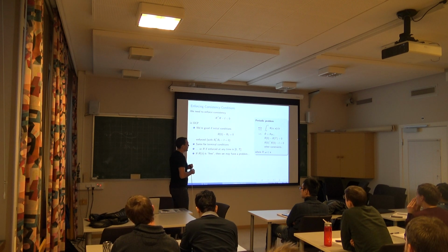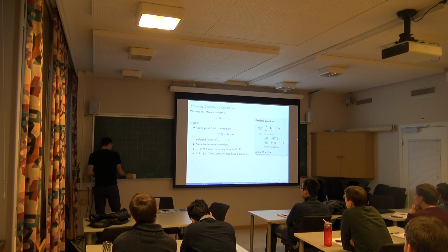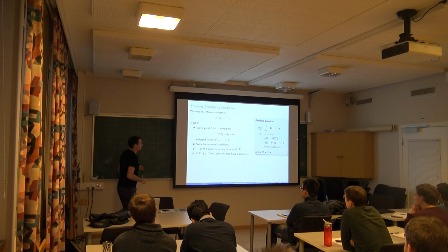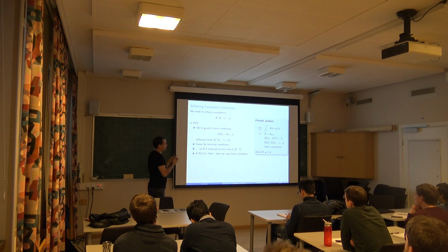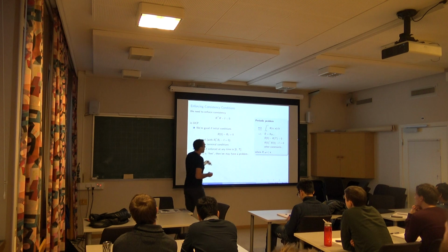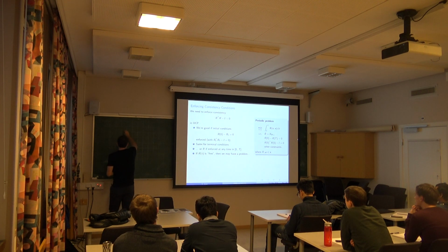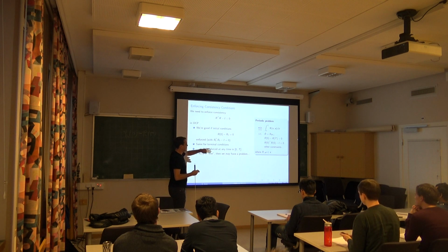Here is an example of a problem. This would be called a periodic problem, for example. The problem goes from 0 to T, and you want the orientation you start with to match the orientation you finish with. So it will be like a periodic maneuver. You want to come back where you started. You could impose that by saying I want my R at time 0 to match my R at final time. That would be this constraint. So it would be like flying a turn and coming back where you started.